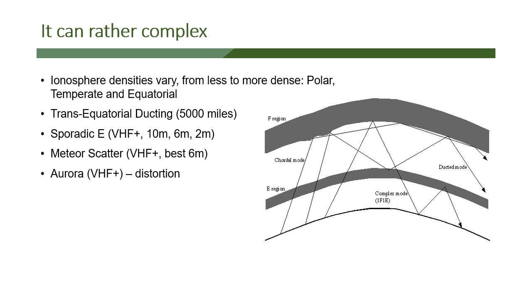Kind of the same line of ionization is the aurora, whether it's the southern or northern lights, which creates distortion, and if it's not super energized, you can oftentimes bounce the signal off the aurora and create a reflected wave. It's not unusual for people in, let's say, Alaska to aim their antennas towards the aurora to reflect back to reach the continental United States.